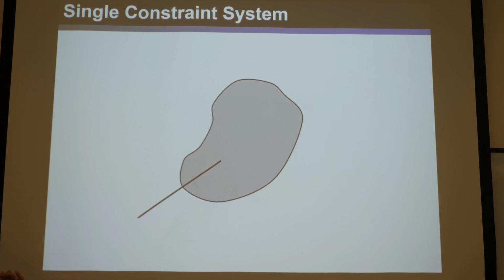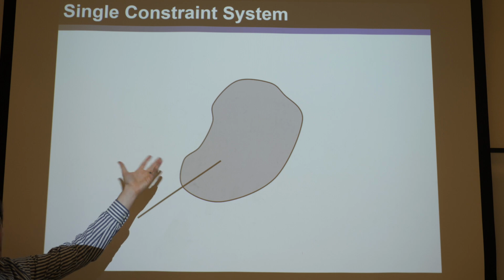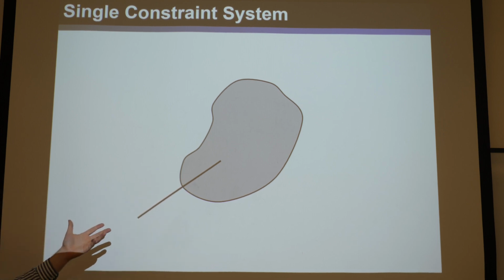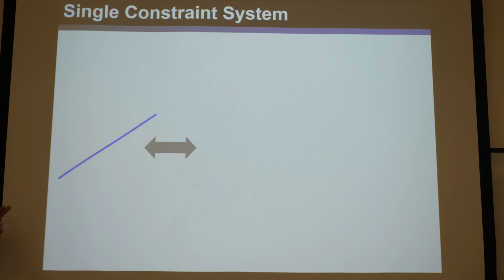But once it becomes actually a constraint system, and you stick this in and ground it on the back, then you could go through the process of drawing the blue line, then finding all the red lines that intersect it, and then finding all the blue lines that intersect that. And my point is, there will really only be one constraint space, no matter where you stick that, or no matter how you orient it, for this case of just a single wire. Okay, so of course its constraint space is this blue line.